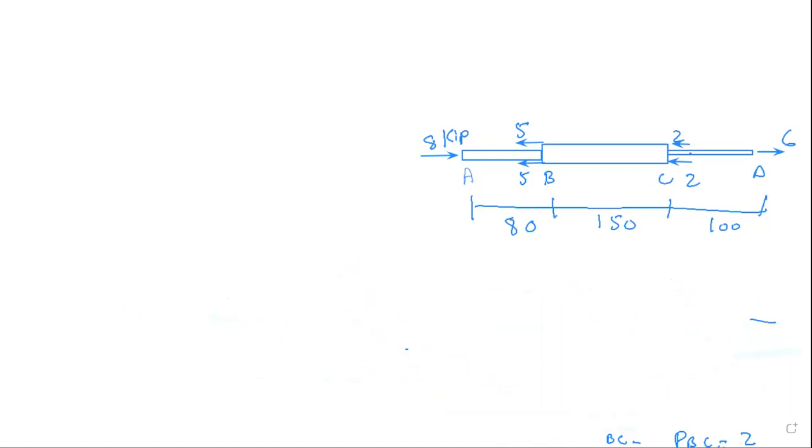Elastic deformation. The formula is PL over EA. So the formula for the elastic deformation is delta equals the summation of PL over AE.